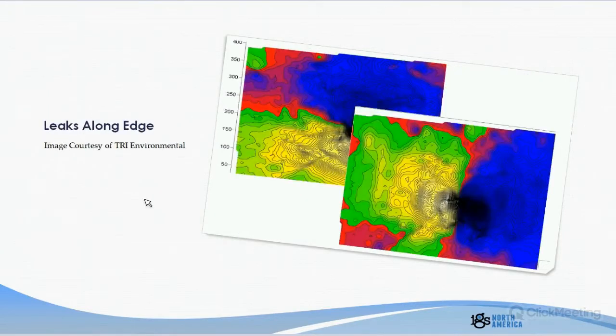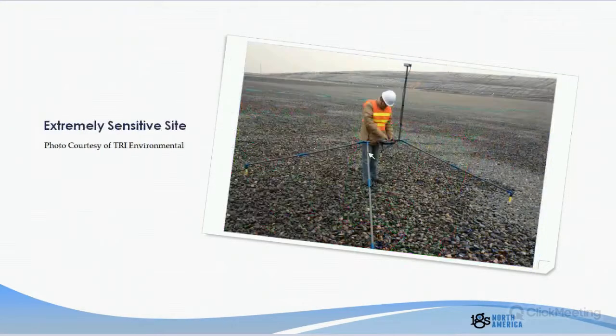At this particular site, we used the double dipole technology where we can measure not only in the direction that we're surveying, but also the perpendicular direction. Let me go back to this slide here. When we're surveying, we're walking forwards with the dipole, but we're going backwards and forwards across the survey area, looking at the voltage across the left side and the right side. But in the background, every time we hit the record button, we're also measuring the voltage across the front feet and the back feet. And so we actually produced 2 maps for the price of 1, essentially.